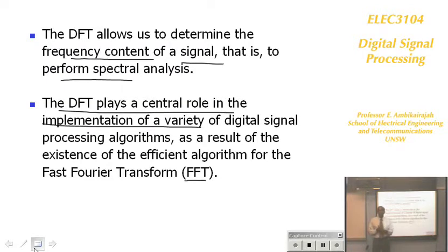You've got two options. One is to write a big equation and solve it, you get x theta, which is a continuous value. Or you say, no, I'm not interested. I'm only interested in the frequencies available in it. So you use discrete Fourier transform, which will only test certain frequencies, whether they are available, and then tells you the amplitude and the phase. And the way of implementing it is the fast Fourier transform technique.